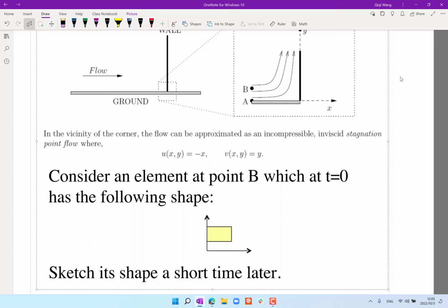It'll be a little more compressed. It'll be a bit more compressed, like in what way? The streamfield widens as it moves along, so that it's going slower, which means the pressure is higher. Yes, that's right. The pressure is higher, and remember we are looking at incompressible flow, right?